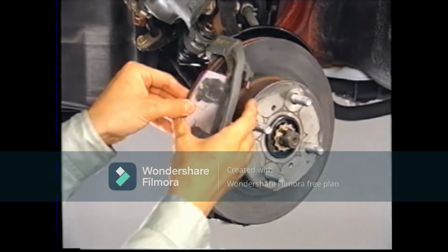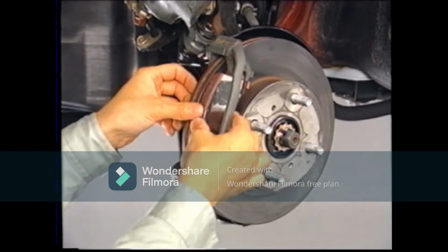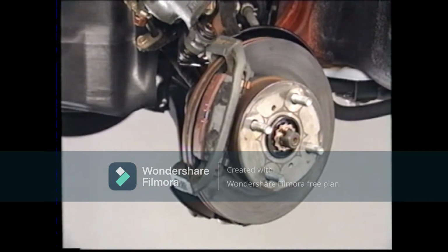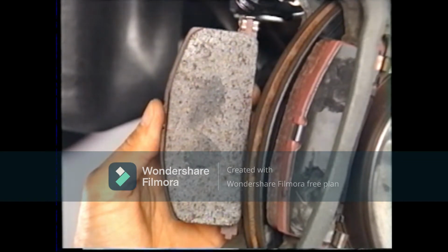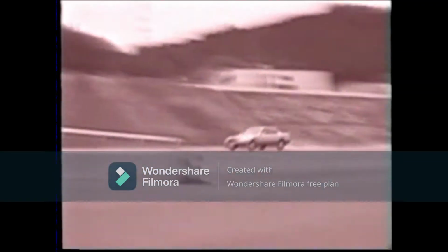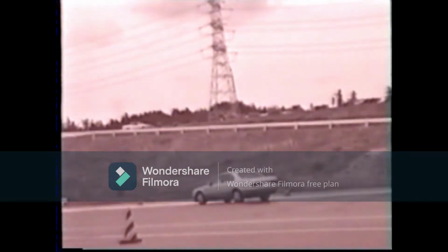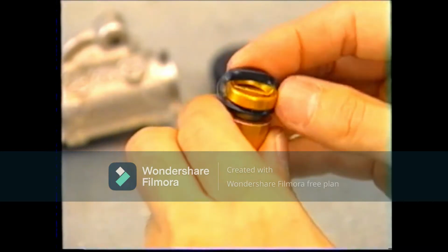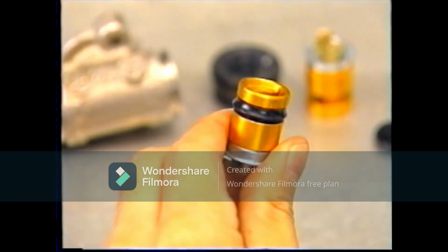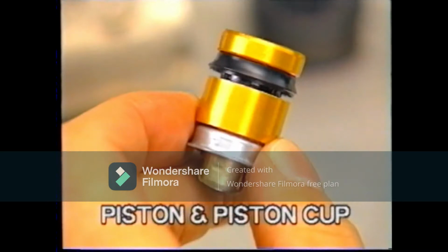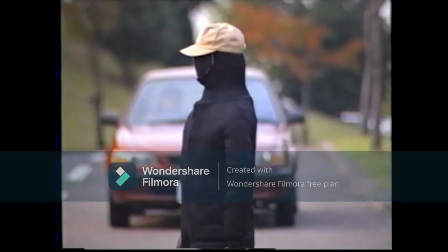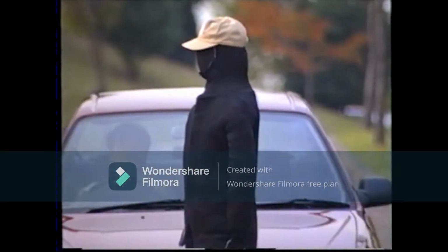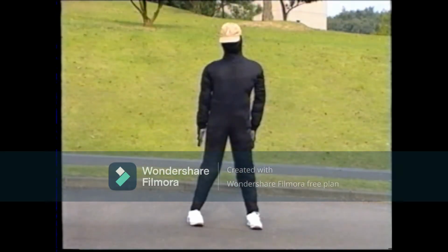Brake system maintenance requires utmost attention and accuracy. Oil or grease left on the lining or pad during maintenance causes brakes to pull to one side. Assembling a small part in the opposite direction causes brake fluid leak. Such carelessness may harm the customer or pedestrians.